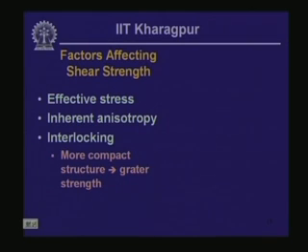Then factors affecting shear strength. What are the factors that affect shear strength parameters? Number 1 is effective stress. So higher the effective stress, as we have noted, the shear stress that the assembly can support is also going to increase.